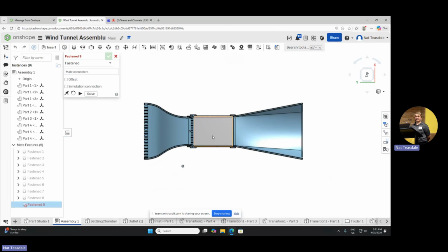So to actually generate the wind or create the airflow, what you're gonna have in the end is a fan here, and that's gonna suck air in. Now, the reason we don't put it at the front is because behind the fan, it's gonna generate a lot of vortices, a lot of turbulence, and that's not good if you want to view streamlines.